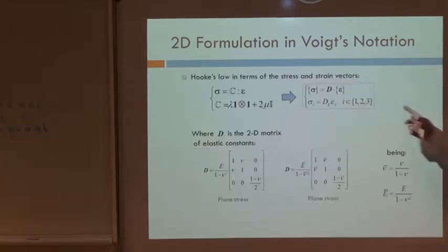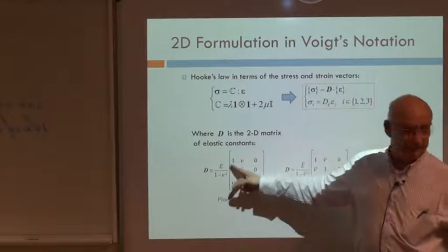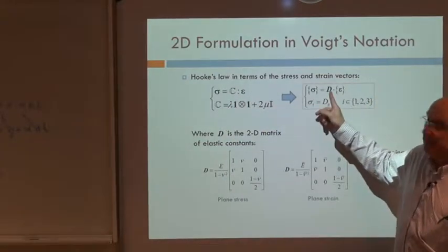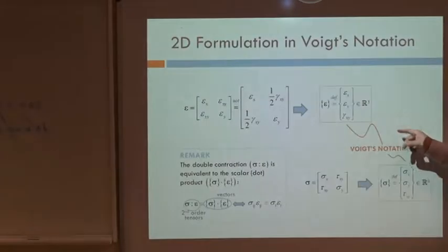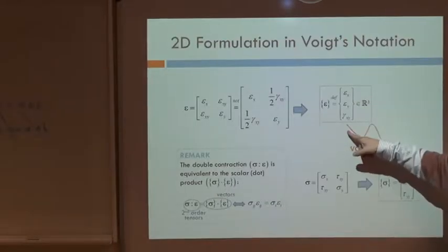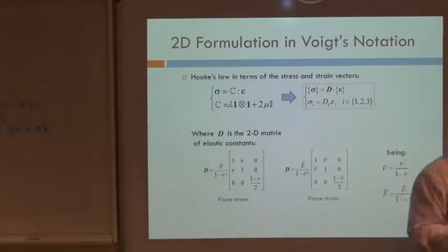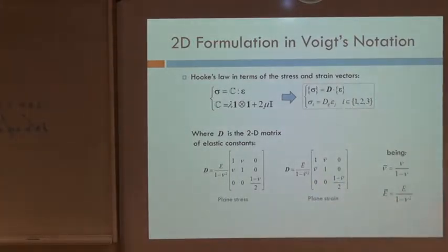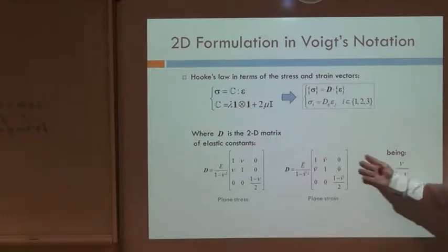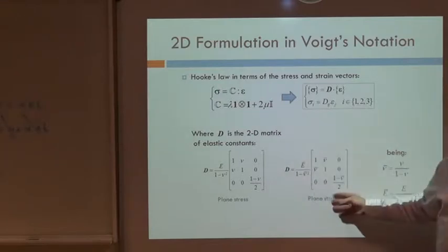So instead of C, we have some D, which is 3 times 3 now, because the strains are just 3 components. Okay, 3 times 3. And here there is a difference, which is specific for plane stress or plane strain. In fact, with the intention of doing things as simple as possible, we can always use the same expression for both.